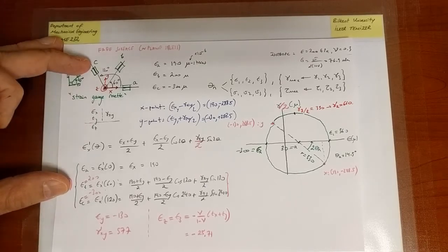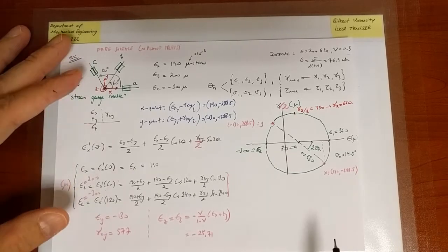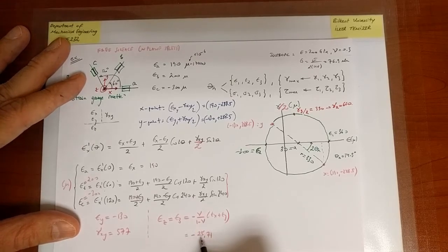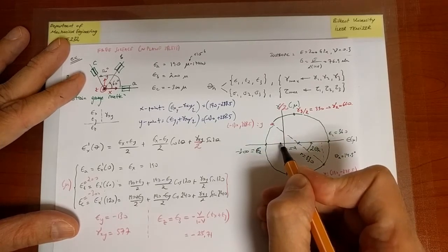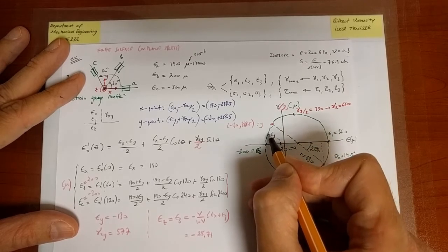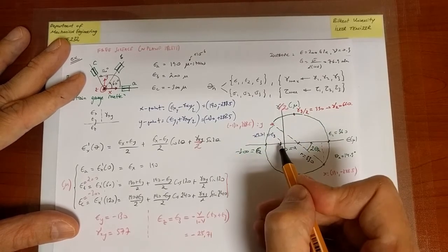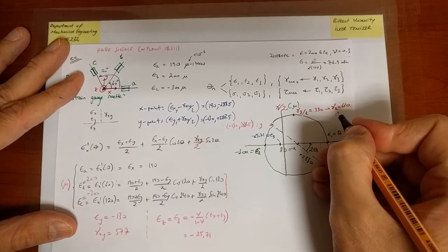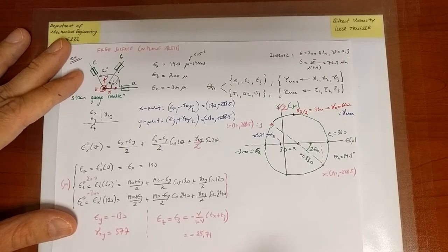Okay, so that is the value of gamma 2. But is that the largest one? I have to always ask myself, well, that's where the third strain comes in. Well, the third strain in this case is minus 25.71. So if this is 300, it's going to be just less than 1/10 of that. So that's where epsilon 3 goes, which is equal to epsilon z, which is minus 25.71. It's quite small, and the circles associated with that are not going to be any more critical. So this value of gamma is actually simultaneously the absolute maximum shear strain.